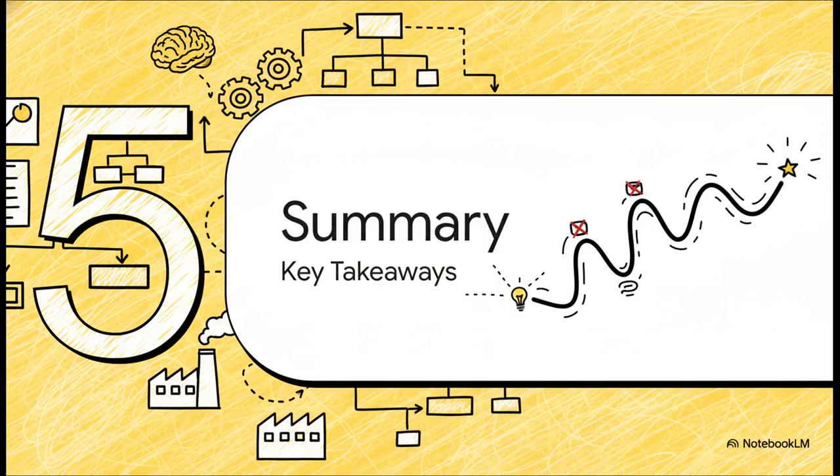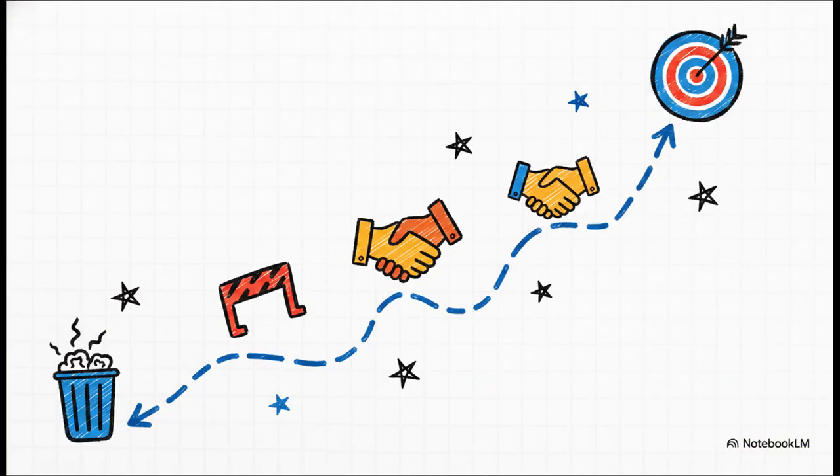Section 5. Summary. Key takeaways. So let's bring it all together. Value stream mapping is not a passive poster on a wall. It's a highly active protocol that visualizes both material and information flow to aggressively eliminate non-value-adding waste. Yes, applying this to dynamic project life cycles like construction introduces massive hurdles: unique designs, fragmented data, and cultural resistance. But as we've seen, these barriers are absolutely not insurmountable. By utilizing dedicated guiding coalitions, running intensive knowledge workshops, and enforcing rigorous standardization wherever possible, you can completely transform VSM from a static manufacturing relic into a highly targeted tracker of your project's ultimate productivity, progress, and cost goals.